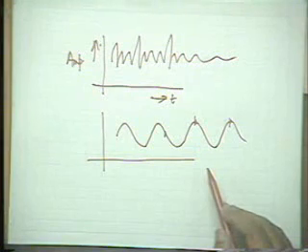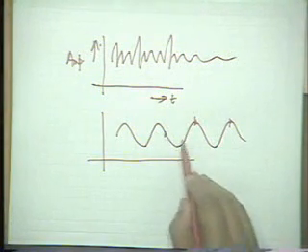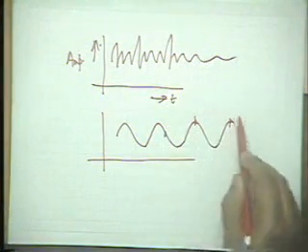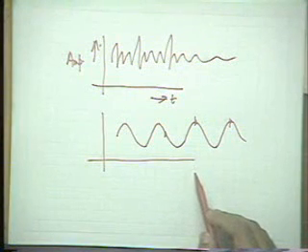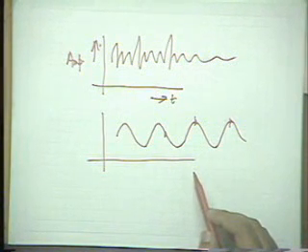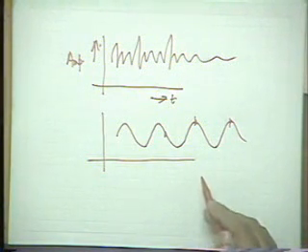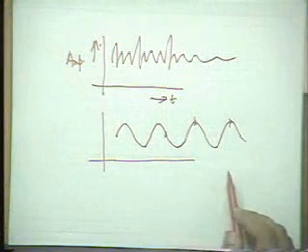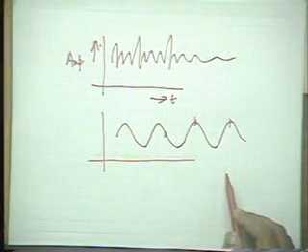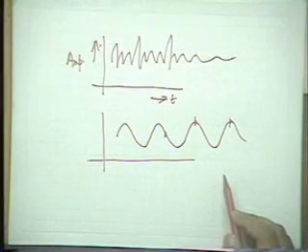These are clearly noise. Some noise has given rise to a waveform like this. So, if we do a low pass filtering of this signal, rather if we allow only the sinusoidal component to pass through the filter, and do not allow the higher frequency components, then very clearly we can get rid of this type of noise, by doing a low pass filtering.